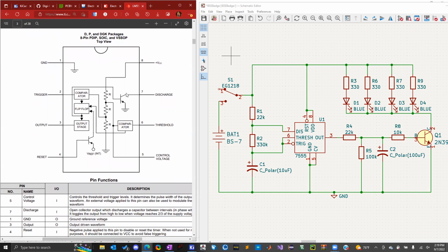So essentially what this thing is, it just has comparators and some flip-flops. If you wire them up in a specific way, you might have learned in your digital system design class, or when you get there, you'll learn about it. With this specific configuration here with the two resistors, this capacitor is going to charge up to the voltage that you're giving to the chip.